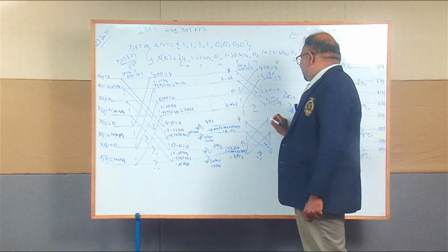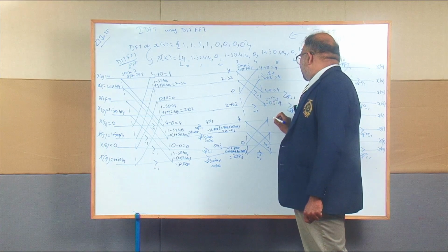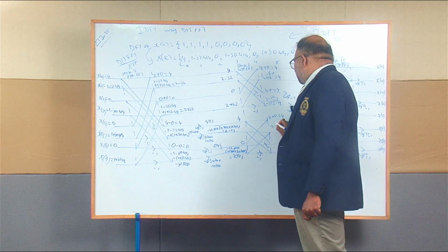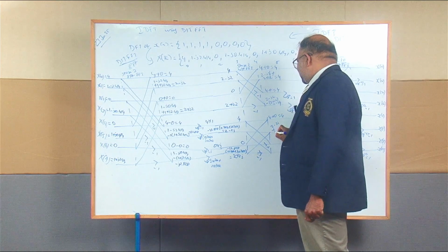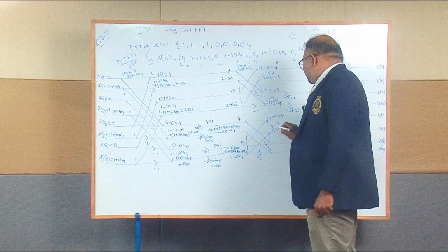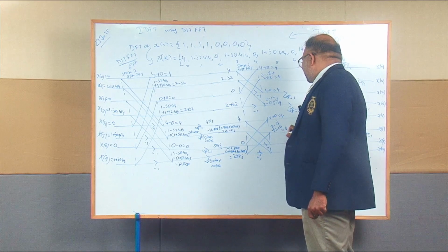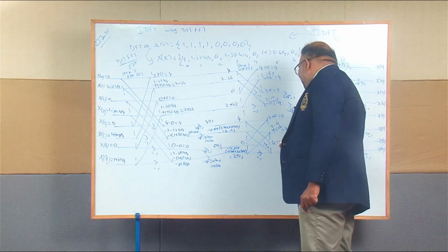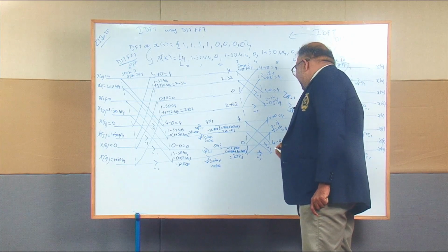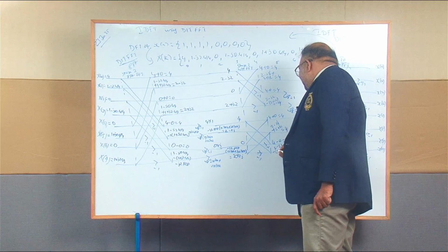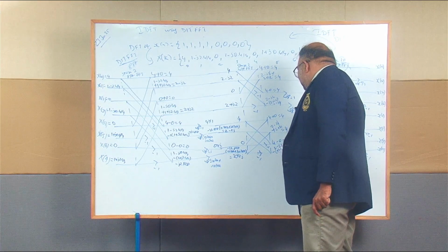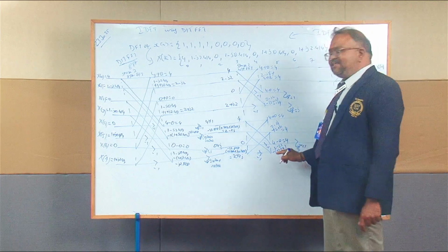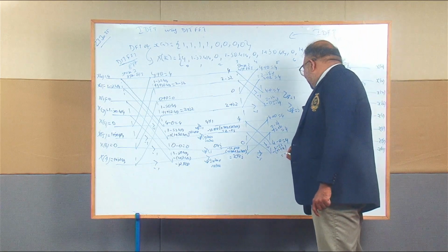Okay. So, next one here, the second stage of the 4-point FFT. 4 plus 0 is 4. Here 2 minus 2j plus 2 plus 2j. These two terms will get cancelled, so I will have 4. Okay, and next, this one: 4 minus 0 is 4. Here again 2 minus 2j minus (2 plus 2j). When I bring in the minus sign, 2 and minus 2 will get cancelled, and I will have minus 4j.